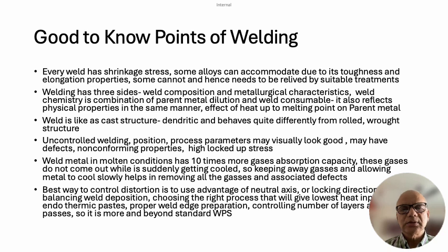So once a WPS is written and accepted, a draft WPS has to be qualified by performing a test called a PQR. And once a PQR is correlated to a WPS, we shall not change any parameters written in that WPS. That's the rule which we must follow for the critical equipments and even for the normal equipments if you want to have repeatability and consistency.